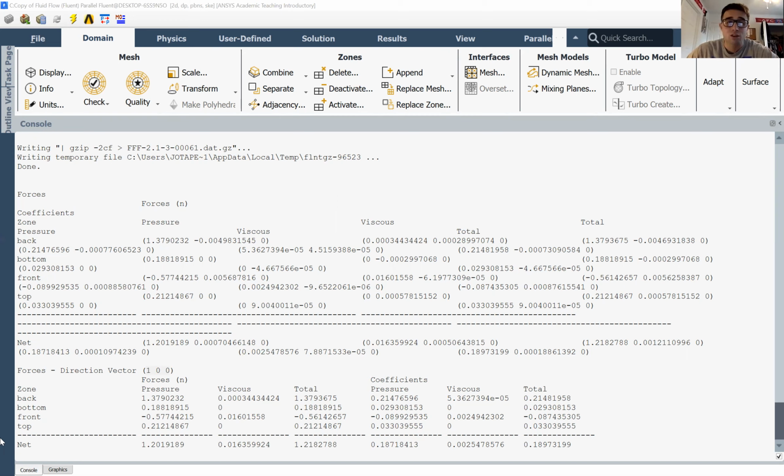Now, in order to get these contours, all you have to do is go to this button here, click contour. You can do the name of your contour, and then there's going to be a little screen that pops up here that allows you to, I'll open it up really quick. It allows you to choose your parameters for your specific contour. So you want to make sure that symmetry 2 is chosen. For this one, it's just pressure, and the higher the number of contours, the more accurate your contour is going to look. So I did 200 contours. So I'll just apply that again just to show you, make it appear. And again, that's what it looks like.